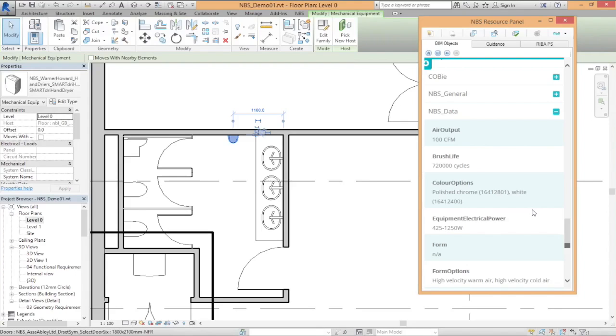And that's part of what COBie, you may have heard about the term COBie, and that's basically just about structuring information in a standardized way, so that when clients get their building in a digital form, they've got standard tools which will read COBie, they can understand what that means, import it into their facilities management systems, and then manage the building far more effectively. The government is trying to introduce a far more effective way of maintaining and managing their built assets. There's a lot of opportunities to improve value and actually optimize how the buildings are managed and maintained.